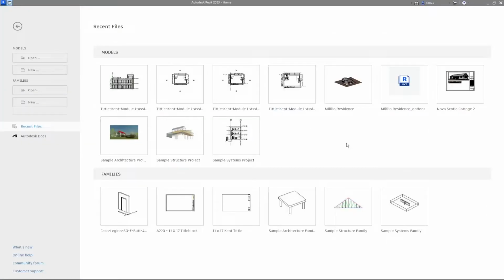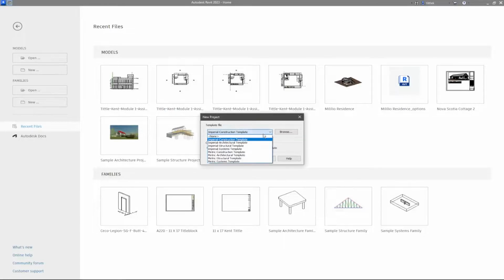So jumping right into Revit, at the time of this video recording, I'm using Revit 2023. Just some quick review. We're going to start with the template and we're going to start drawing the walls first. We need a new model based on a template. So we're going to say new. Again, we are an architectural course, Arch 220, so we are using an architectural template. We are always drawing our buildings from the view of an architect. And it's a new project, not a new template. So we want the project, hit OK.